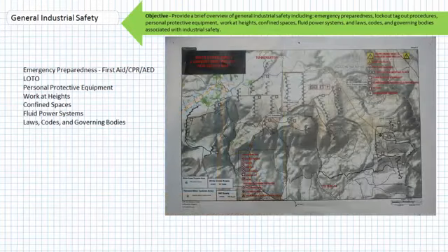Every team needs a map with every single wind turbine on it, as well as all roads, inclement weather shelters, evacuation routes, and the location of special purpose medical equipment like stretchers, backboards, and AEDs. On the back of the map should be all emergency procedures and contact numbers. The map needs to be laminated, and technicians need to be responsible enough not to let the map blow away. Don't laugh, it happens. Wind farms are windy, go figure.